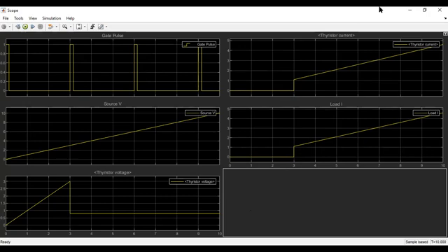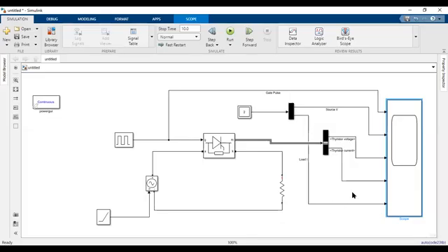So this is how we perform the VI characteristics of an SCR using MATLAB. Obviously, we were using the Mux parameter. We are not using it right now, to see every single graph separately. Previously, we have already seen the comparison of both the currents, thyristor current and the output current, in the same graph, and this is separate.